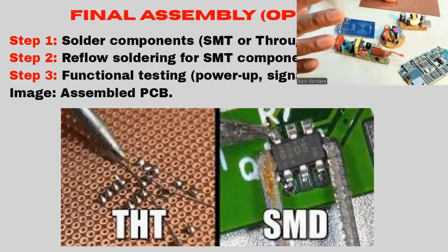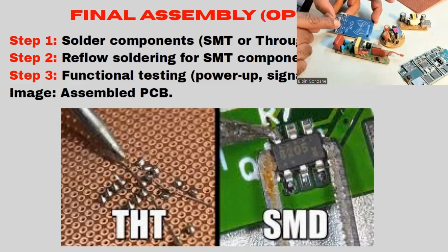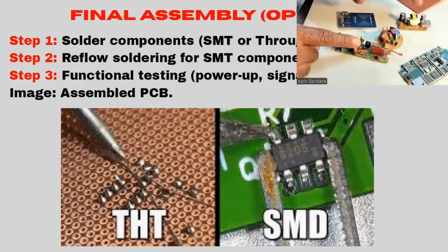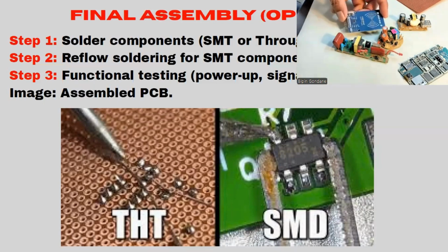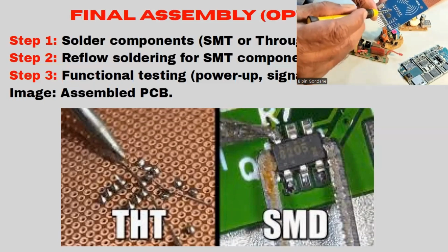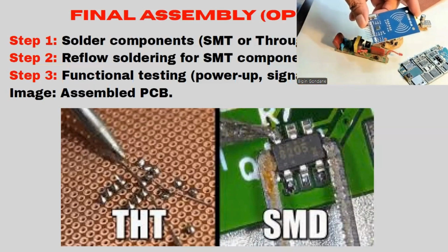This is the PCB. Now this is optional. Either you can give the PCB to the company who has asked you to manufacture it, or if you are a manufacturer, then you have to assemble the components. That means the parts have to be fixed. These are the parts which will be fixed onto the PCB, and the soldering will be done. Two methods, SMT and THT. Through hole technology we use. SMT means surface mounted technology. Surface mounted means what? These are all surface mounted devices. On the same surface, the components have come. That is called a surface mounted device.